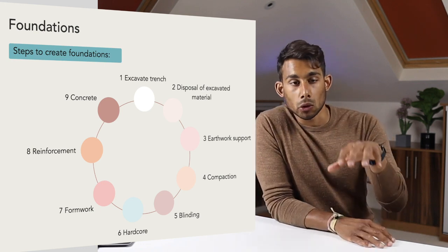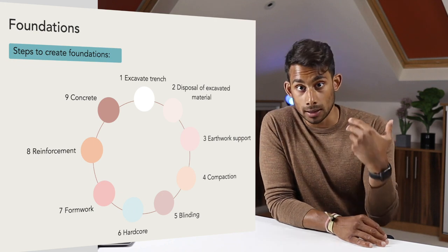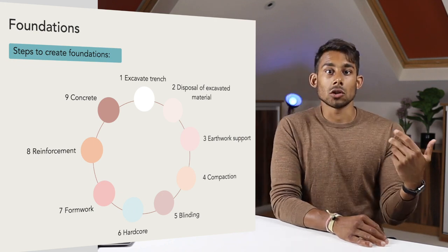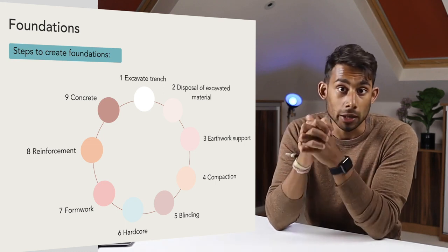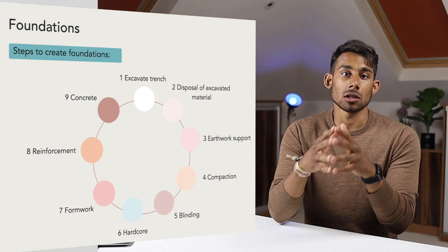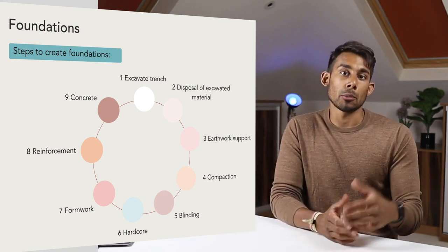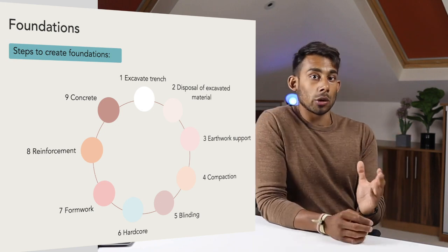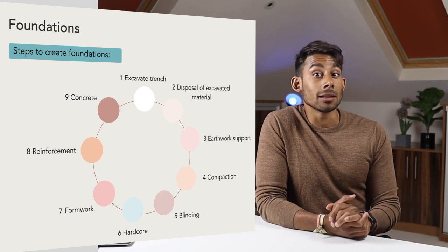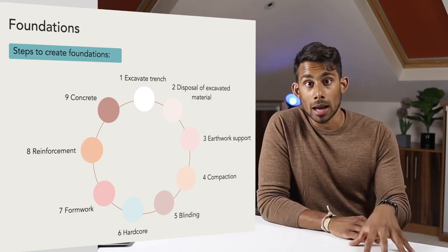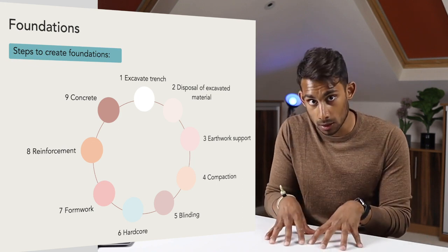Next, it's about curing your concrete. It is important that the concrete doesn't dry out too quickly as it hardens, as this could cause a weak, dusty surface. The easiest way to achieve this is to keep the slab damp by covering it with plastic sheeting, making sure the edges are sealed to prevent wind tunneling effects. This is particularly important if temperatures are above 20 degrees Celsius or if there is a stiff breeze that could dry the surface. Also, if temperatures are likely to dip below 4 degrees, a frost blanket or similar should be used to insulate the slab and protect the surface from frost.